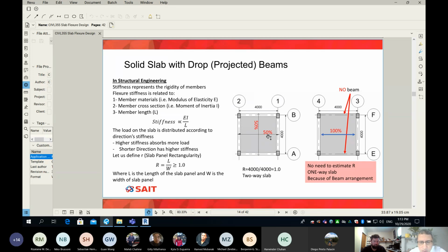And we talked about if I add some loads here in the middle of the span, the slab will simply have to take the load and then place the load into the beams. This is called load path. So my discussion going forward is the load path. When it comes to the load path, it depends on, number one, the beams. If the beams are surrounding the slab from all sides, it means the slab is supported on four sides. So that's one factor. And the other factor is the shape of the slab.